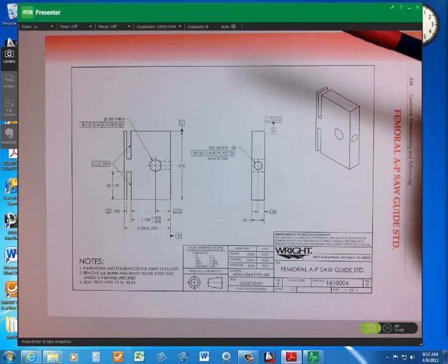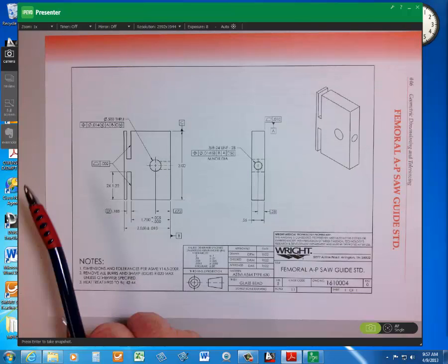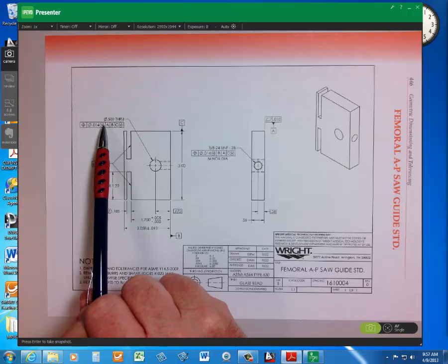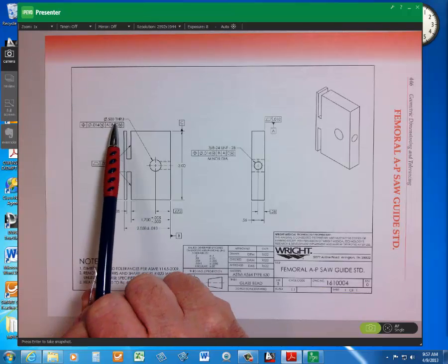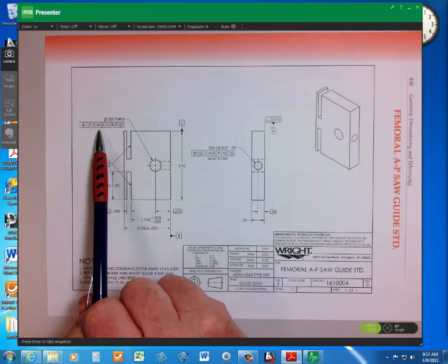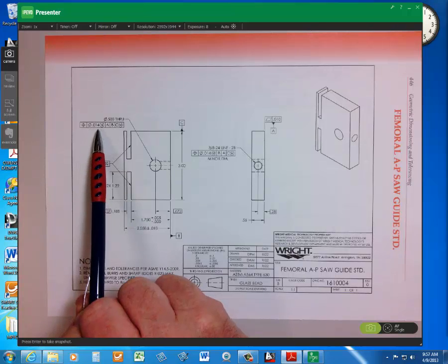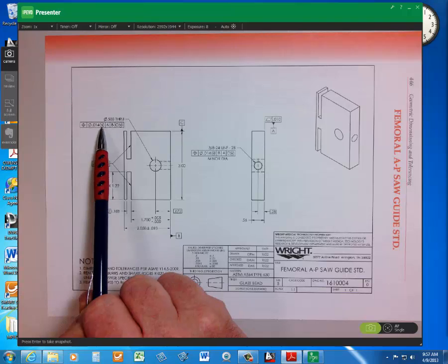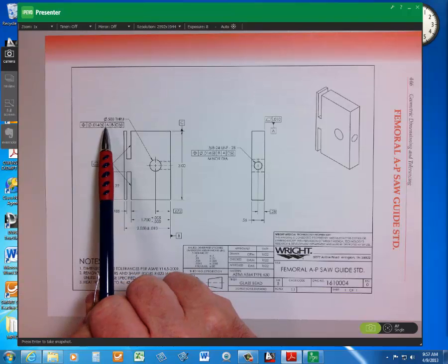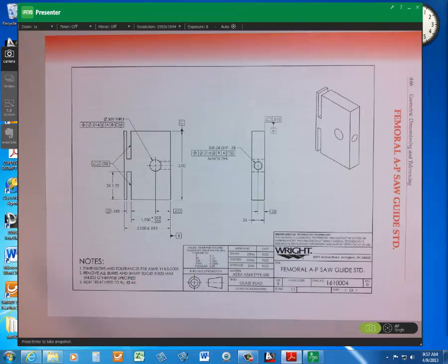All right. Explain the meaning of the information in the feature control frame. The half-inch diameter must be a true position within 14 thousandths diameter tolerance zone at max material condition, related to A, B, and C at max material condition, or max material boundary, excuse me. Provide the positional tolerance and virtual condition.